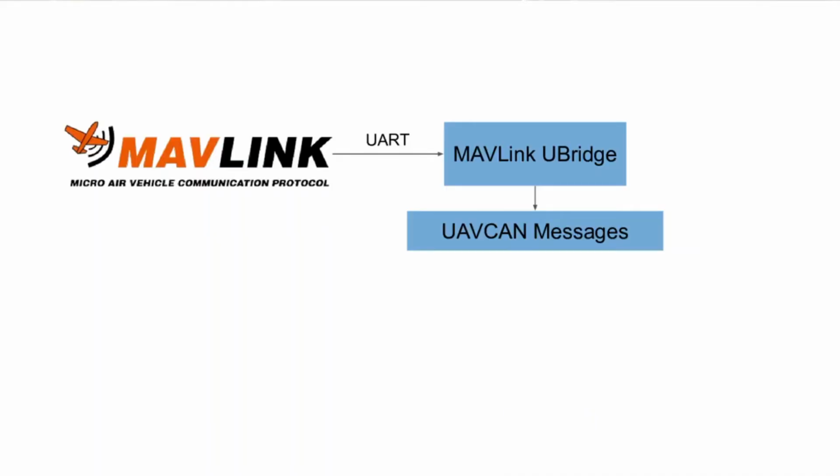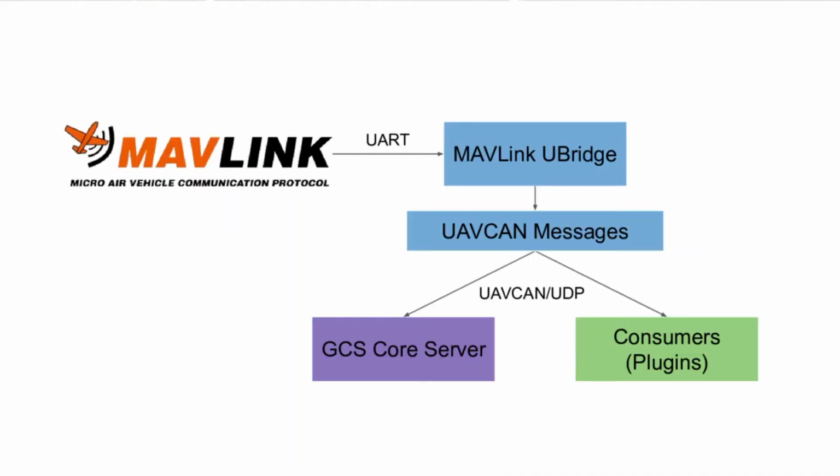The next step was to write the actual implementation for the DDS using PyUAVCAN. Specifically, we developed code to create a node and connect to the drone over UDP, along with a number of asynchronous publisher functions. Each of these functions listens for updates published by the drone to a certain telemetry, mission control, or other service topic, creates a UAVCAN publisher with the corresponding UAVCAN type, and then publishes it onto the internal UDP network. Something to note here would be that topics are identified by configurable numerical subject identifiers, or port IDs.